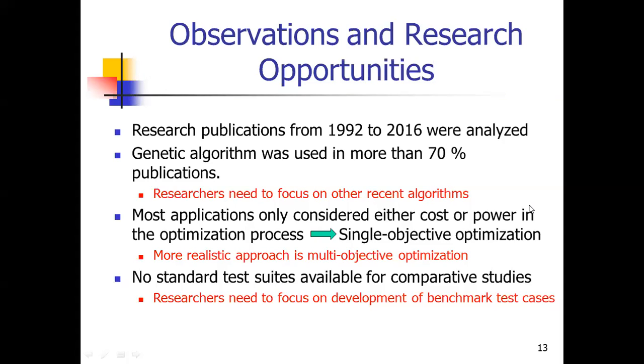For example, the turbine tower that you have, what we call the hub, on which the turbine is installed, you cannot just put a turbine at any height. You have to calculate the optimal height where you get the maximum air. Now we also have a technical limitation that you cannot just install a turbine a kilometer or 2 kilometers above the ground level. It cannot go beyond 140 or 150 meters. That's the maximum. And for each 10-meter increment in this turbine tower, it's more than $130,000 US dollars. Just a 10-meter change in the turbine and the tower height, and that's a tremendous amount of investment.